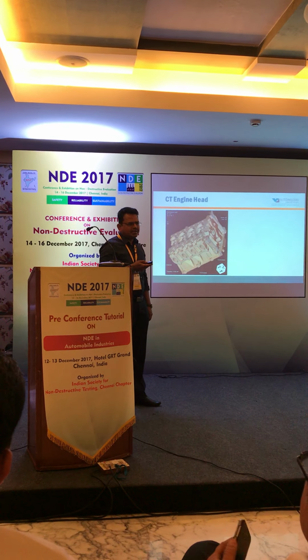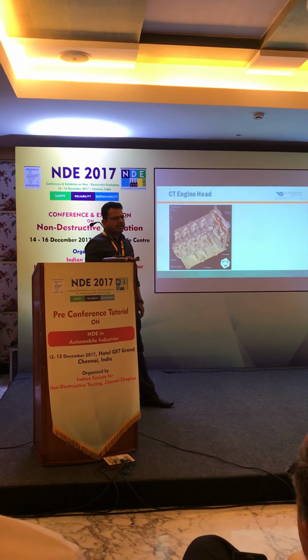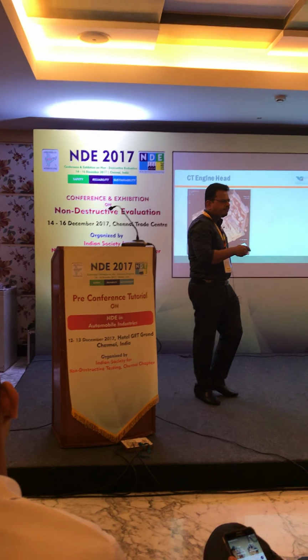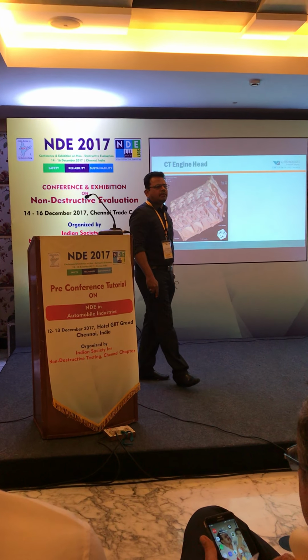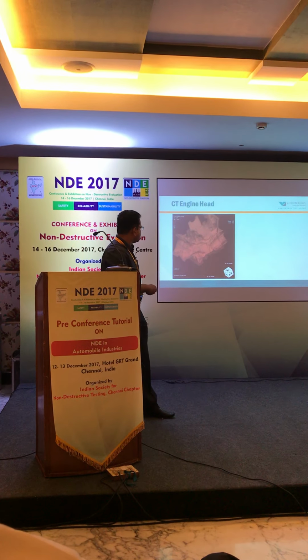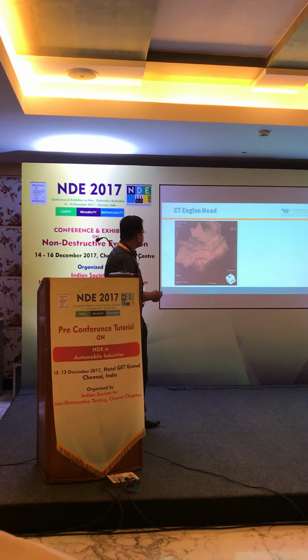on a high energy rather than 450 or 320, because we might get some artifacts on a 450 kV, if I'm not wrong, Mr. Wolf. And on a 3 MeV or high energy, we get very good results. This is how the transparency of a 3D image looks. This is the defects.